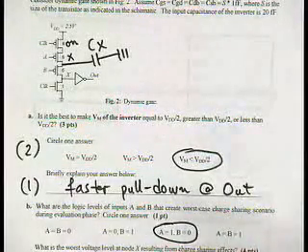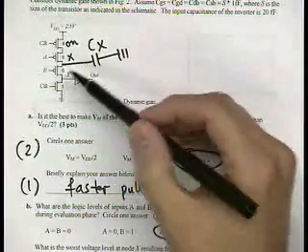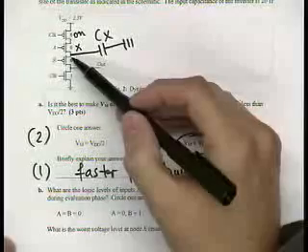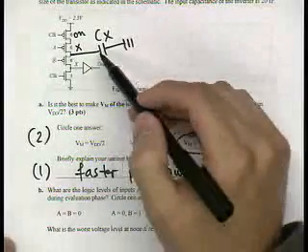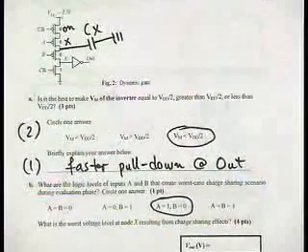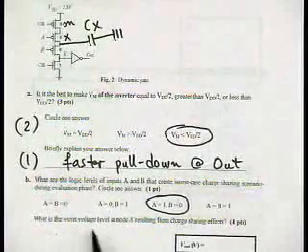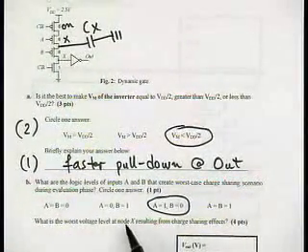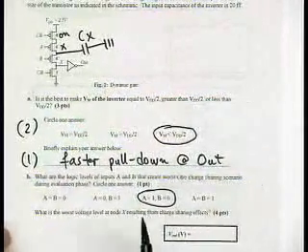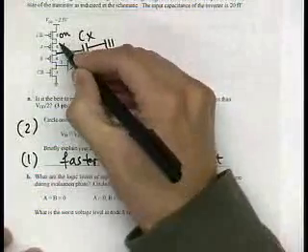A is equal to 1, which turns off this transistor, B is equal to 0. And we assume that this capacitance was initially pre-charged, so that you have VDD initially over here that needs to be distributed down here. So now, in order to find the worst case voltage at this node from the charge sharing effect, what we need to do is to first figure out, oh, this is Y, node Y, sorry.